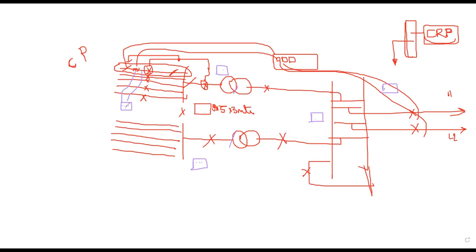Now only a few cables run to the main control room, for the SCADA communication. SCADA is lying in the control room, and only the communication cables are pulled to SCADA from these panels. So the cable trench cost and the cable length decrease, but here you increase the civil cost of the buildings.